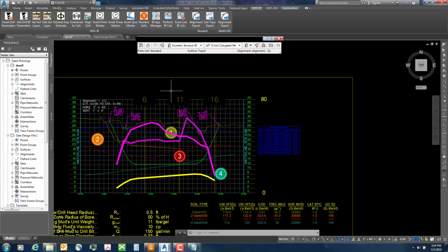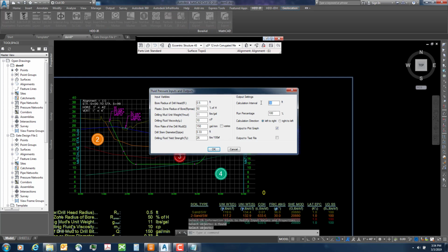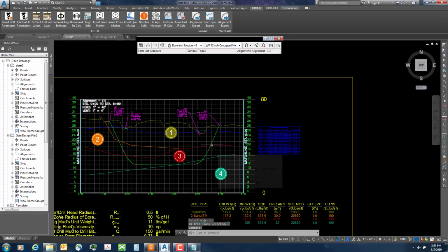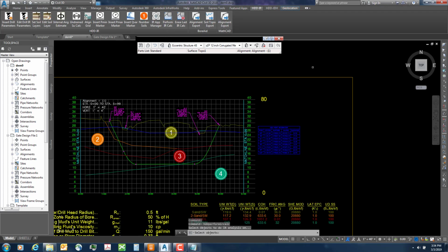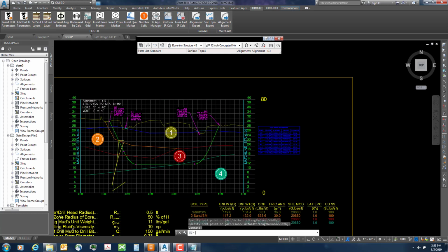Now, do you see these lines here that say 6, 11, and 16? Those are your iterations. So starting here, I'll tell you what, let's change our interval to a smaller interval. So I'm going to erase the calc that it just did. I'm going to come in here and edit. So now instead of doing an interval every 30 feet, let's do one every 10 feet. Give us a little bit smoother graph. Take a little bit longer to do. So I'll perform my arc out and pick all the objects again. So now you'll actually have more intervals.